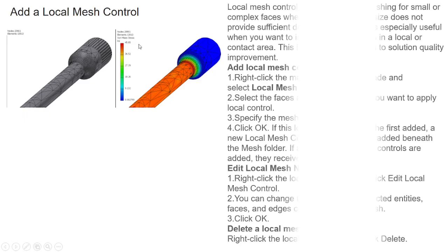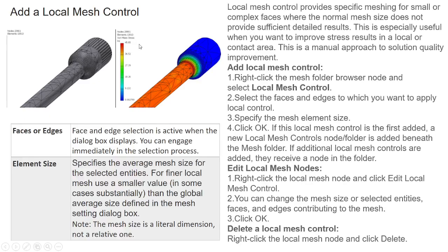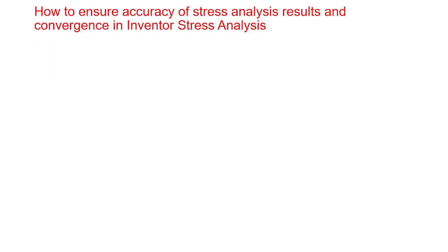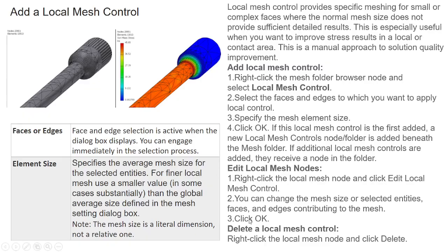We can achieve this using finer mesh, smaller sized mesh, greater finite elements. Under our control, we select the tool of the software and set a smaller sized element for such parts.